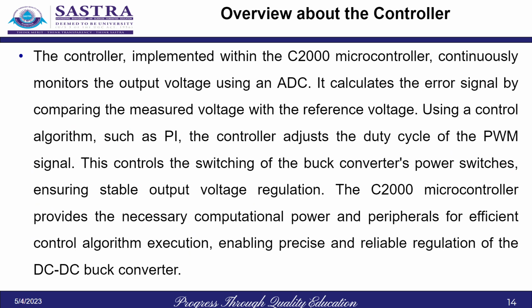Now, in this system, we use a control algorithm such as PI. We could also use PID, but PID controllers amplify the noise in the electrical system, which is why we use PI generally for most of the electrical systems.